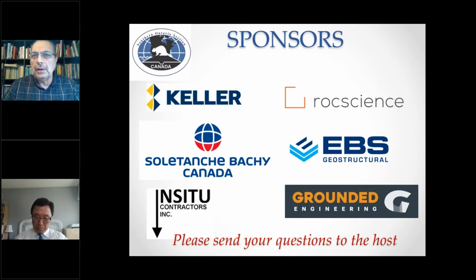between the contiguous piles. So you need to do these French drains and collect the water into deeper wells and increase your discharge capacity of these pumping pumps, I mean.